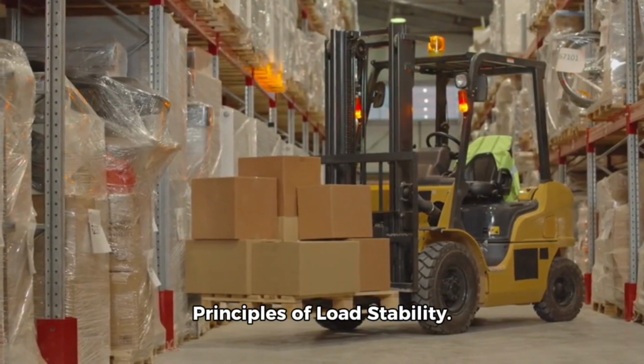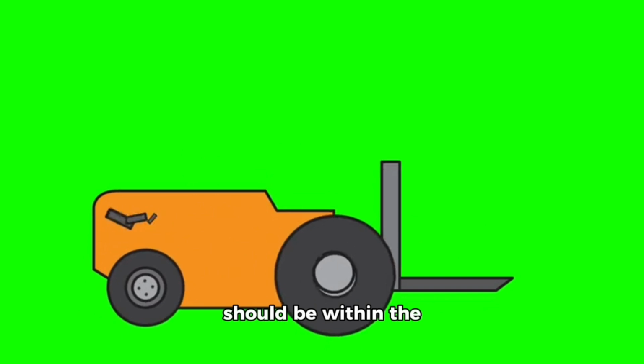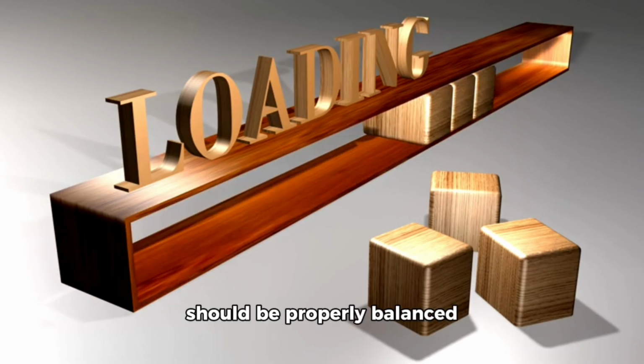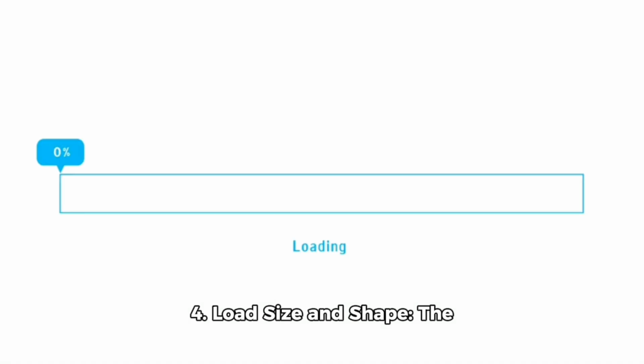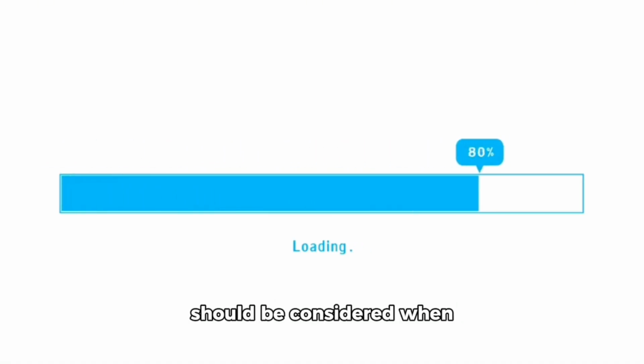Principles of load stability. 1. Center of gravity. The center of gravity of the load should be within the forklift stability triangle. 2. Load balance. The load should be properly balanced on the forks to prevent tipping or falling. 3. Load weight distribution. The weight of the load should be evenly distributed on the forks. 4. Load size and shape. The size and shape of the load should be considered when handling to prevent instability.